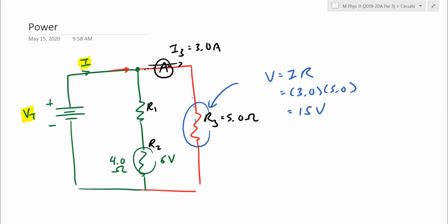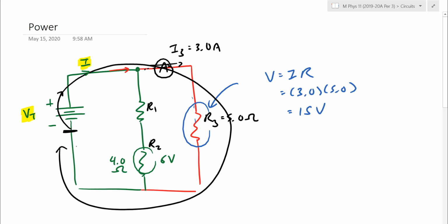If I look at Kirchhoff's loop rule, it said basically by the time I arrive back at the slide, I better have used up all my voltage. I picked up some voltage from the battery. If I consider the particles that travel through the bigger loop, so travel through this red branch, red pathway, I only actually end up traveling through the one resistor. If I'm able to lose 15 volts before I get back down the slide, how much voltage did the battery have to supply you? Well, in that case there, great. We now know the battery is 15 volts. That's the advantage of doing the loop rule here. Around any loop, we have to make sure we've used up all the voltage.